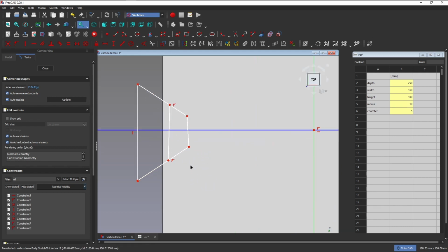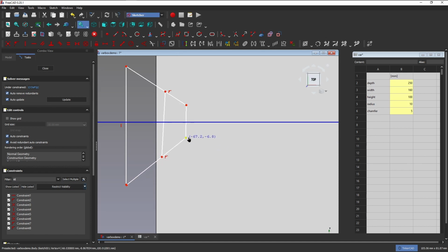All right, and I'm going to check to make sure these are actually attached. Because that can happen where you place the lines close, but they're not on. Ah, there's an example. So this would give you an error. If you left the sketch like this, it would create an error. Actually, I think I will create that error just so I can show you what it looks like. So if it ever happens to you, you'll know what to do. So just making this symmetrical real quick.